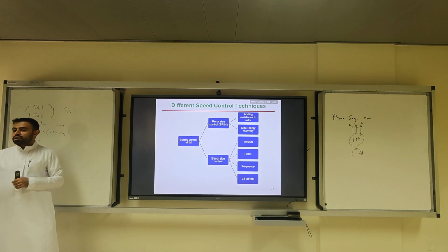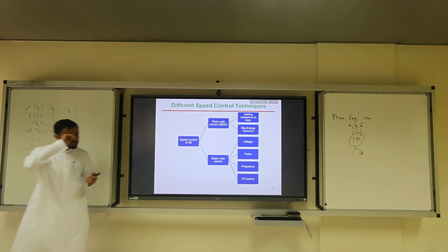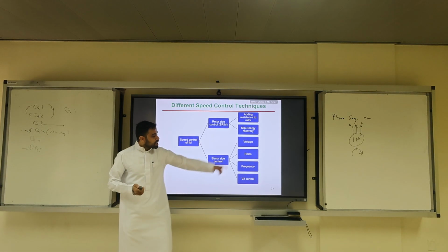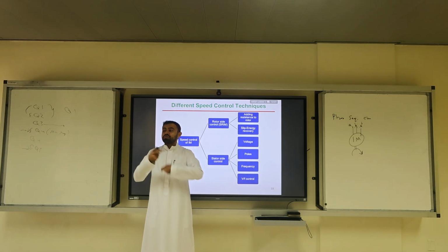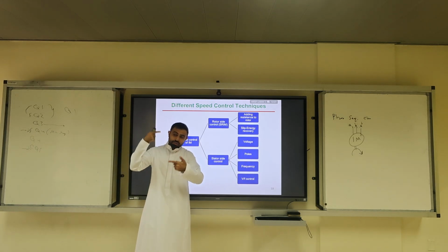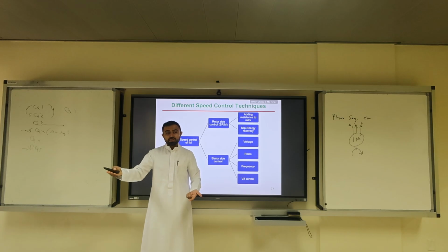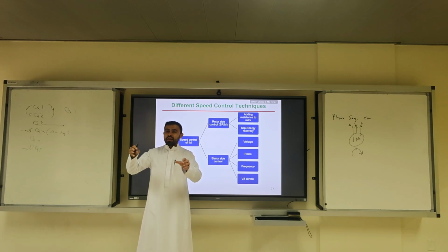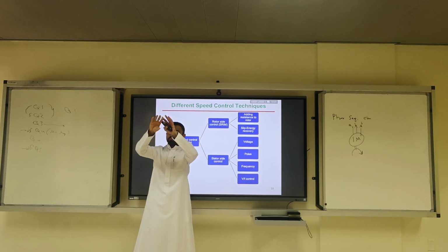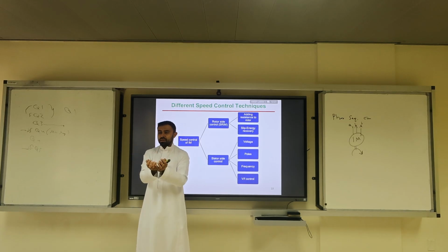It's not permanent; there is no permanent magnet induction motor. I'm going to ask a question in the test. An engineer claimed that he or she is manufacturing a permanent magnet induction motor. Is this a good engineer or a bad engineer? Bad engineer. That doesn't make sense. So changing poles means changing the windings. If you change the windings of the stator, you can change the number of poles. And you will notice that a 4-pole machine would have 4 clusters of windings across the stator.